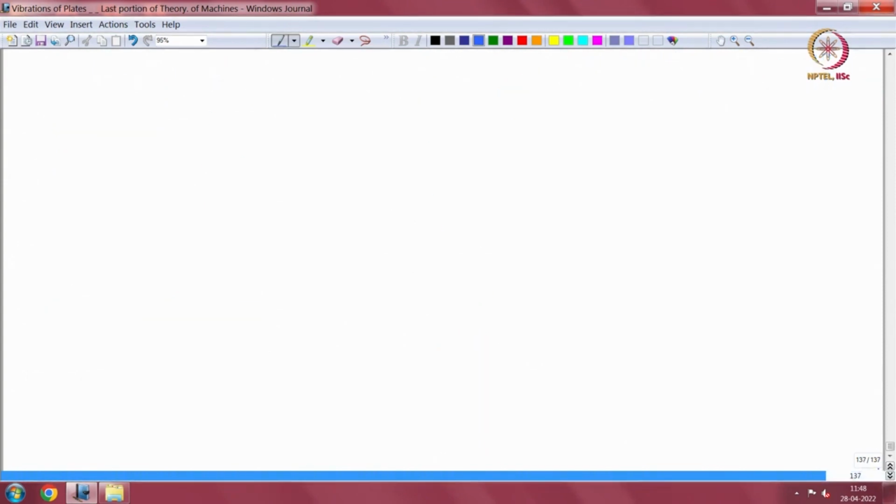Now, here the book takes the same example of a clamped supported beam, where the support is now implemented using a spring with increasing values of stiffness, and again the lambda values are presented. This lambda is the length times m omega square by EI to the power 1/4. Okay. So, let me give you the table from that book.